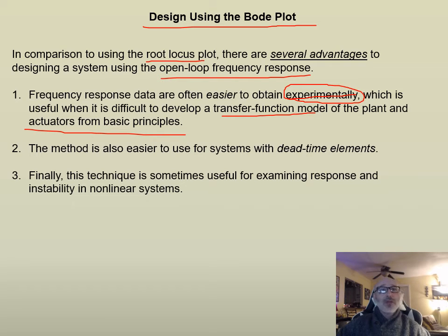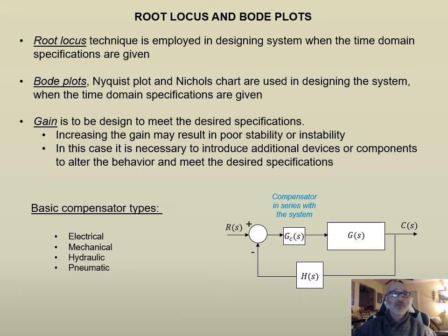Number two, the method is also easier to use with dead time elements. And three, finally, this technique is sometimes useful in examining the response and instability of nonlinear systems. A lot of the systems out there are not going to be perfectly linear systems. They're going to be a nonlinear type of system, and examining the response from that is going to be a lot easier to do using this Bode plot.